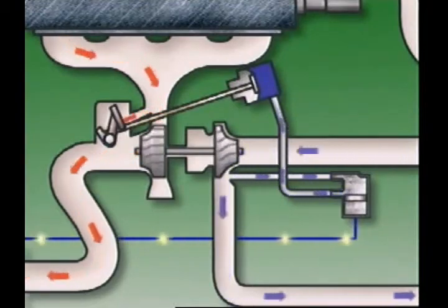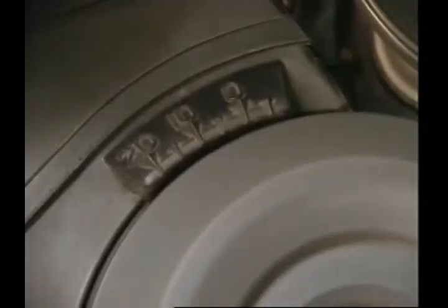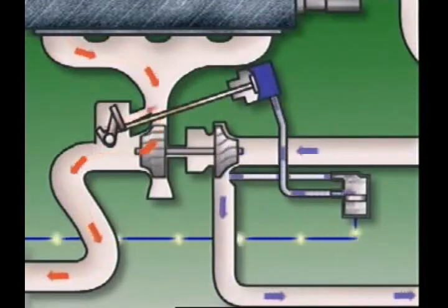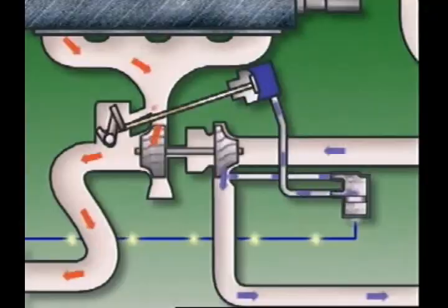As soon as knocking is detected, ignition is retarded, which works immediately. Reducing boost takes longer, but as soon as it takes effect, the control unit returns ignition timing to its optimum value.